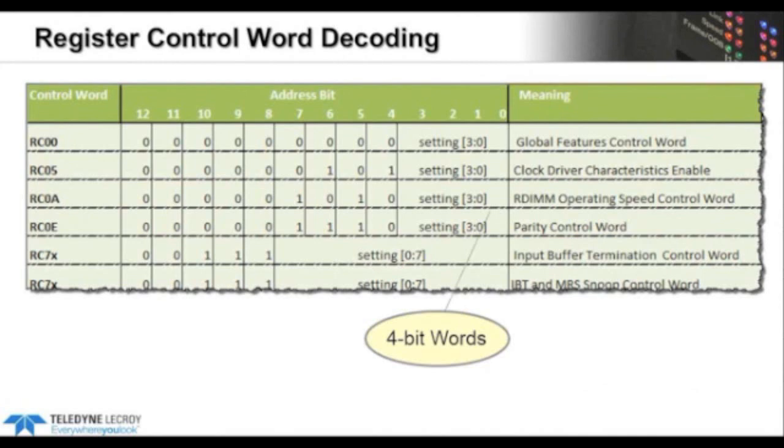One of the main roles of register control words is to tune the output side of the register chip. So these outputs route signals, your command, your address, directly to the DRAM. All right? There are hooks to set the speed, to enable parity checking, turning off chip selects that aren't getting used. There's lots of controls.